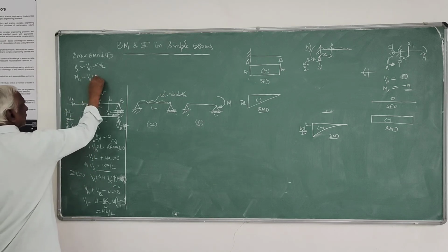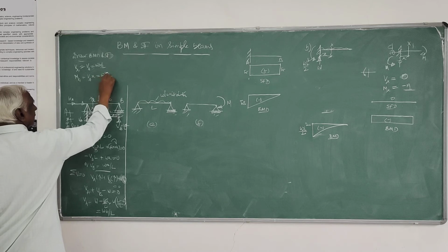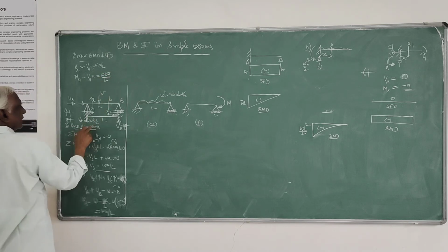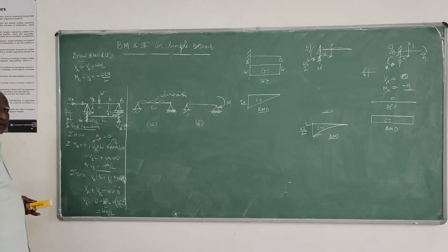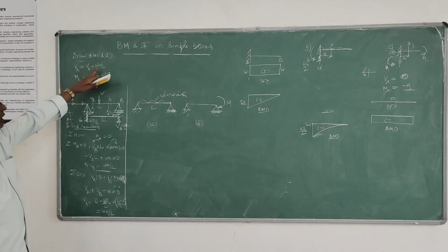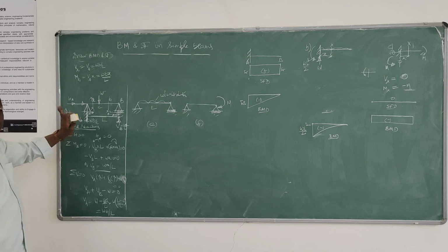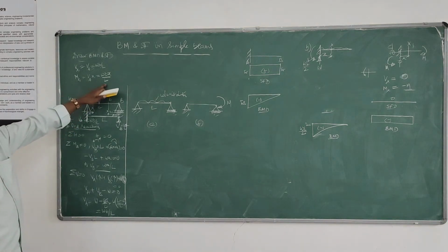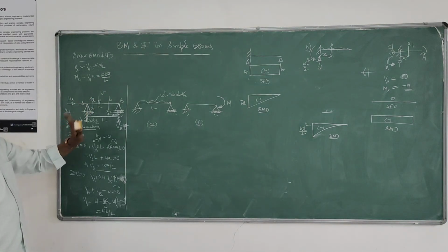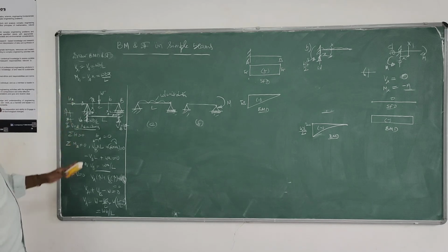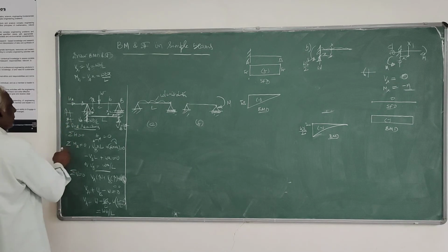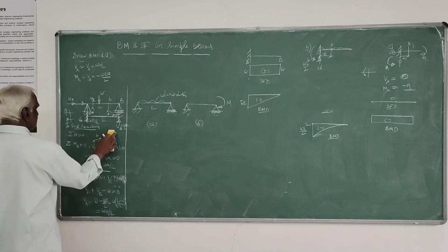So it is Vx into positive, that is WBX by L. WB by L into X. So this is of the form y equals C only, that's constant. Here, this is y equals mx. It's a straight line. That's all. So you plot Vx.